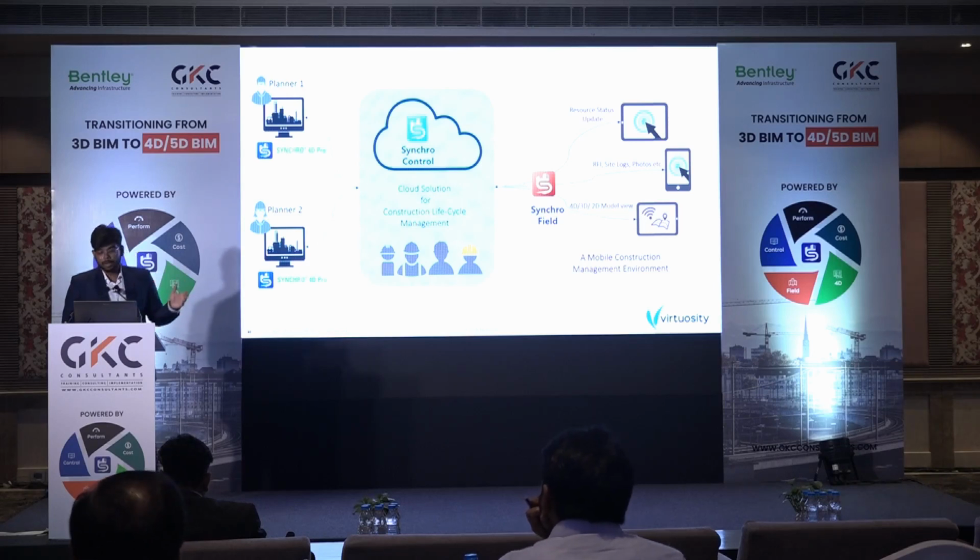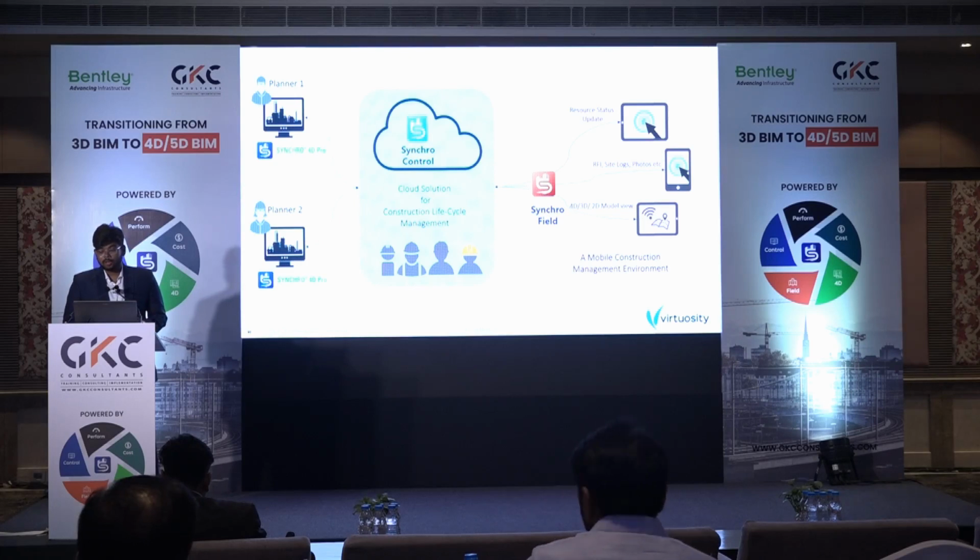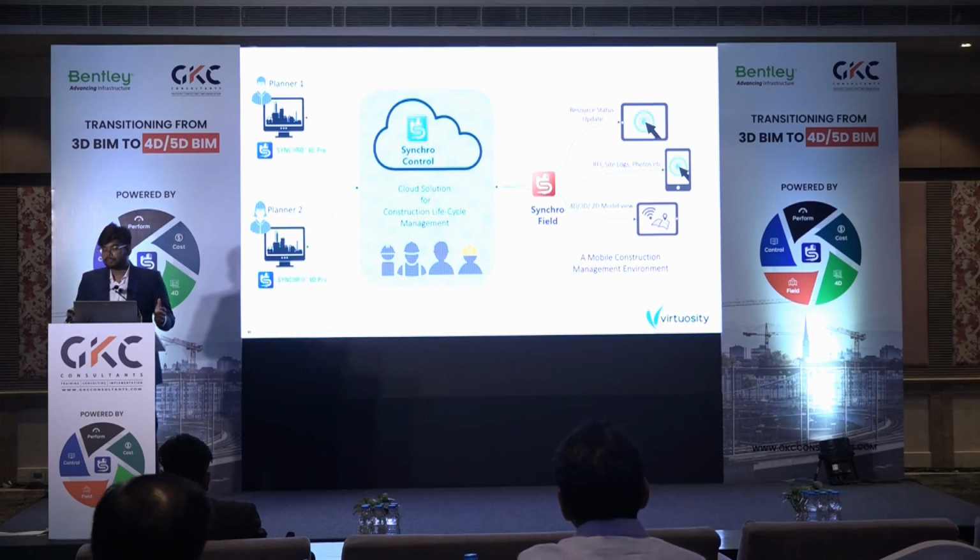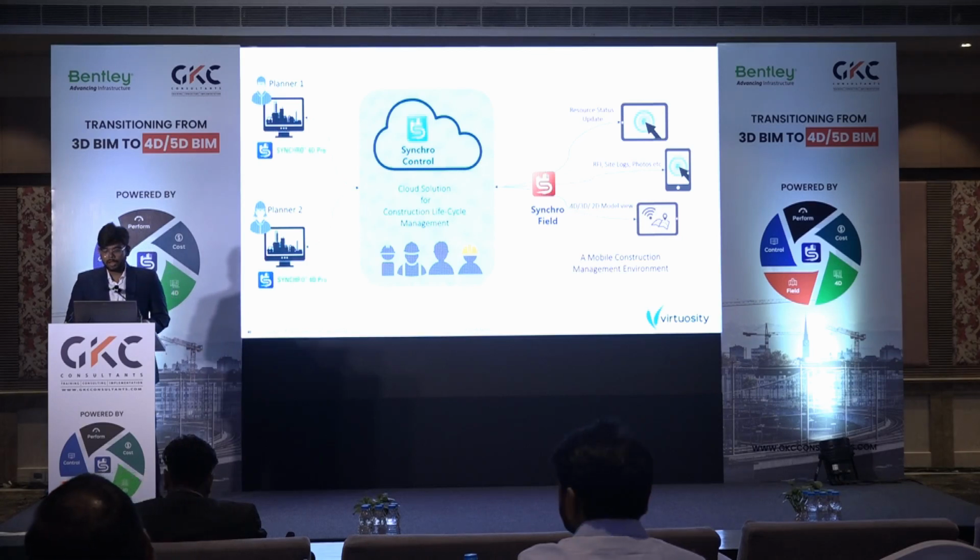For that, they can use the mobile application called Synchro4D on their handheld devices. They can not only review 2D drawings and the 3D model, they can actually review the 4D model of how the construction is going to take place. Furthermore, they can upload photos, videos, site logs, RFIs, or any forms they want to update from site. These forms are also connected with the 4D model or the 3D model that you have. And the other important aspect is that when they are updating information from the construction site, they will also update the resource status and the progression status at the resource level.